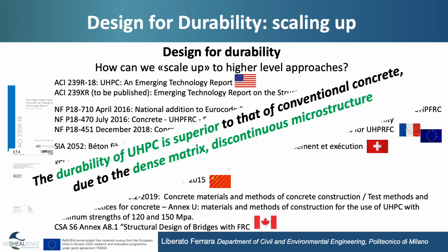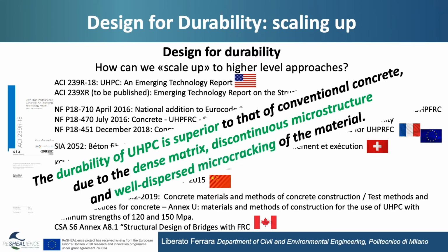But also it's stated that the durability is superior thanks to well-dispersed micro-cracking of the material. And this is durability in the cracked state. So we have to distinguish this. Because these materials are surely intrinsically more durable in the uncracked state, but their way of working in the structure, thanks to a well-dispersed micro-cracking, will make them durable also in the cracked state, more durable also in the cracked state.